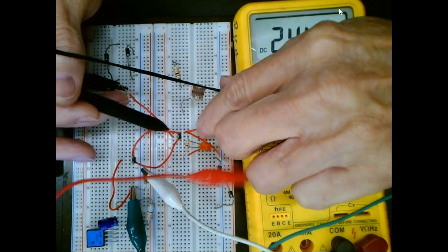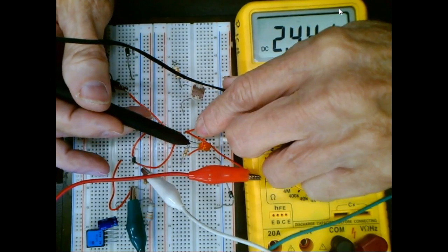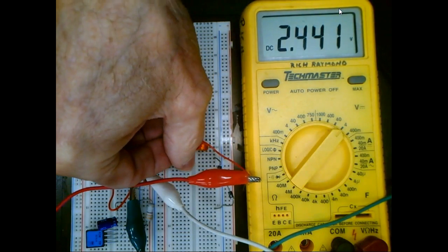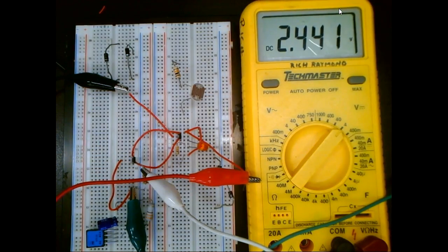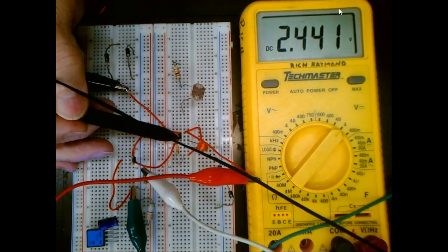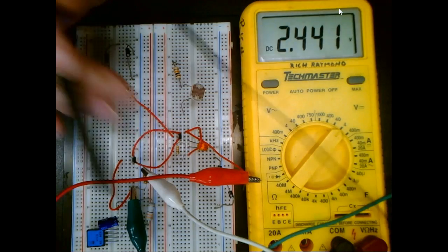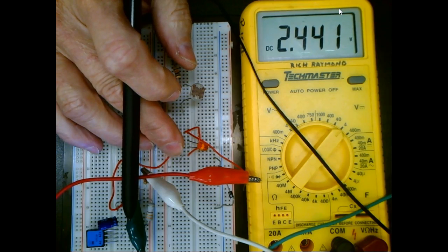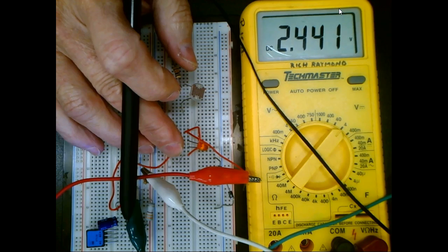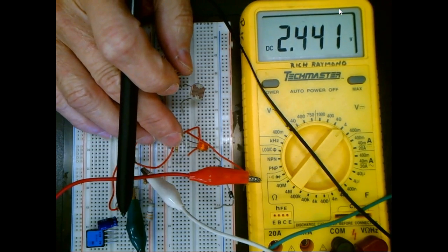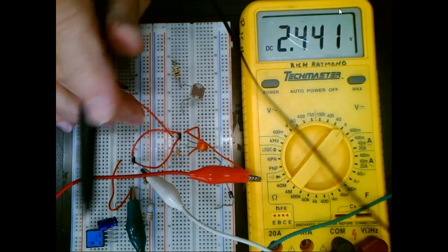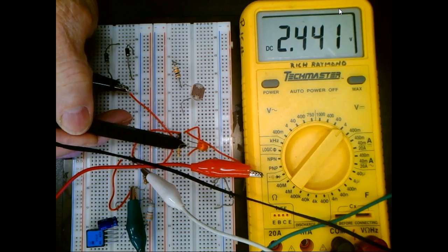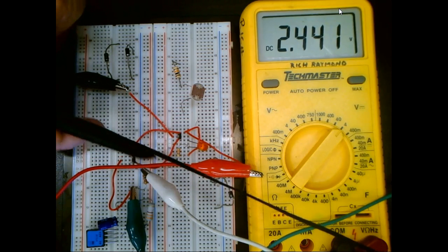But unlike my other one here, I have my output. So here's my resistor. I'm using a 1K resistor. No, I'm not. But that's okay. I'm using a 330 ohm resistor. I should be using a 1K, but what would be a 1K? And so this is the orange, brown. So it's a 330 ohm. But I've got its other end connected to mine's. So this is a sourcing sensor, right? That makes sense.